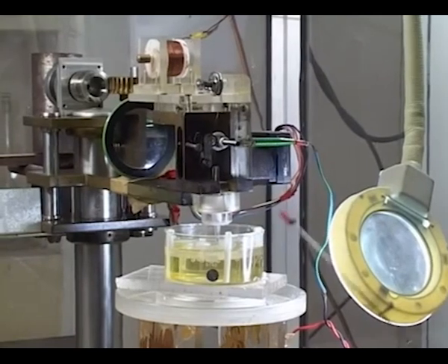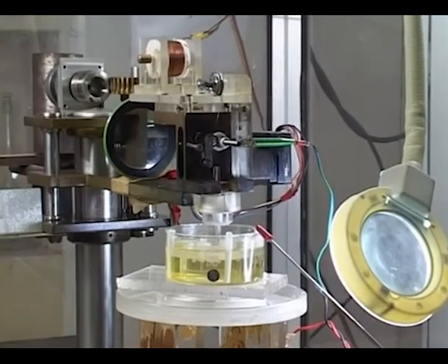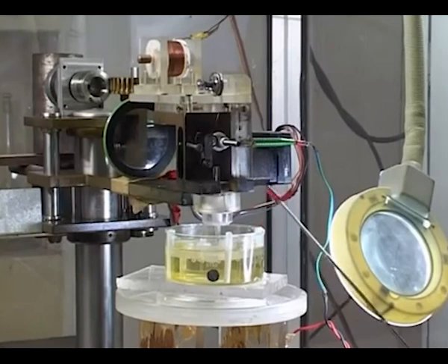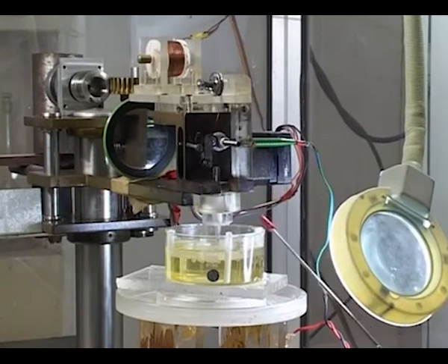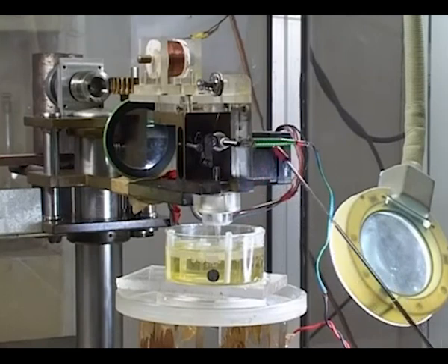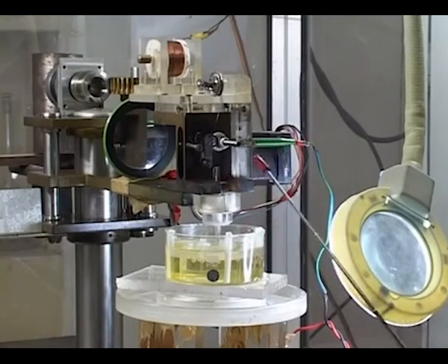And though this machine is fabricated for the spark machining process, with the change in electrolyte, the change in power supply and the scheme, the same machine can be used for electrochemical machining, and electrode discharge machining by using kerosene as a dielectric in the electrolyte cell, and for electrochemical spark machining.